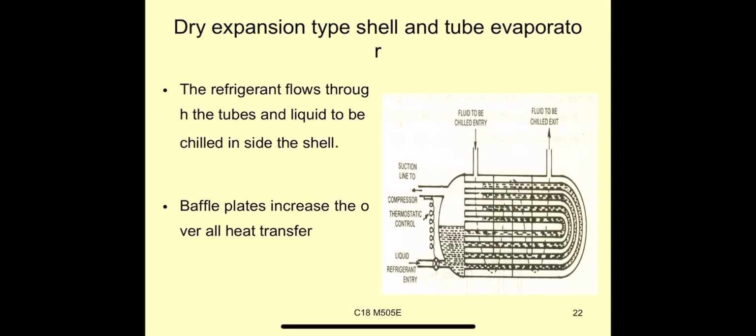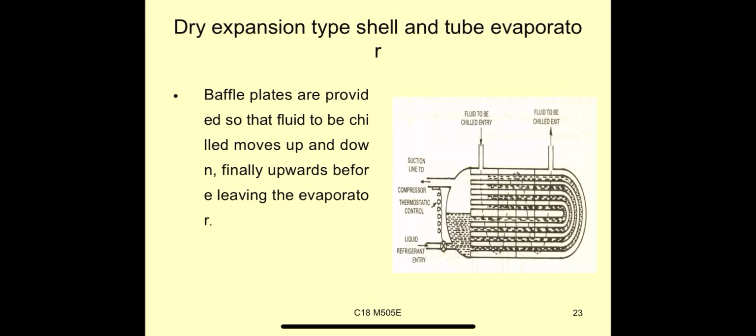Baffle plates increase the overall heat transfer. Baffle plates are provided so that the fluid to be chilled moves up and down, finally upwards before leaving the evaporator.